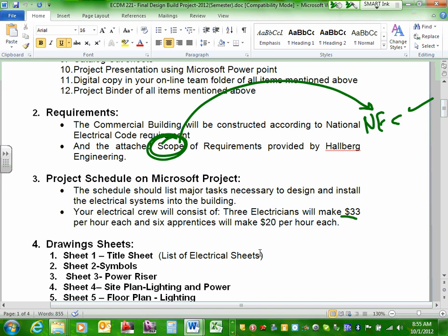Brian, when I asked about needing a low voltage lighting control panel, you said, where does it say in the code that I need a low voltage lighting control panel? It doesn't say anywhere. Now you're going to go from meeting the code into exceeding the code and doing an engineered project. Can I have thumbs up, Chad, before they understand now? Why are we going to put 3 receptacles on a 20 amp circuit when we can put 9 receptacles on a 20 amp circuit? We're going to go from meeting the code into what? Exceeding the code. Everybody can see that shift? We were meeting the code in the residential. Now we're going to exceed the code.